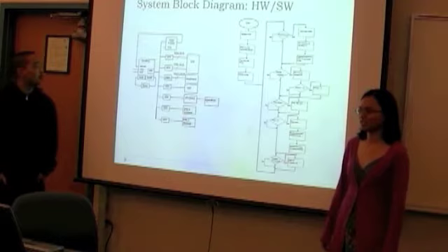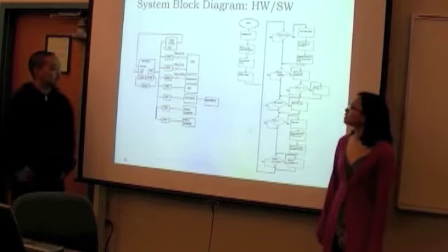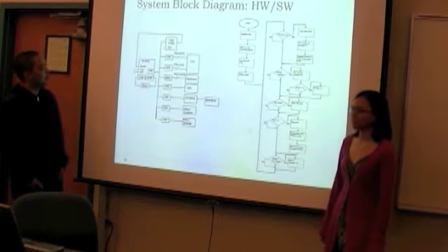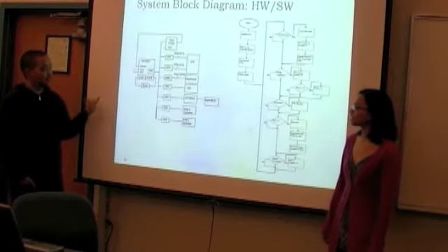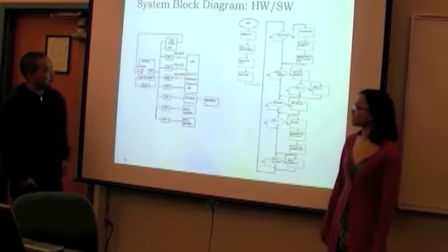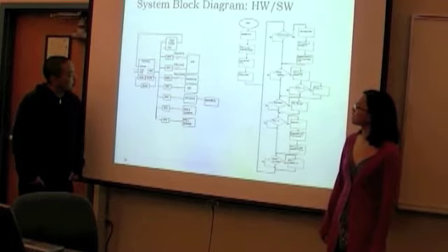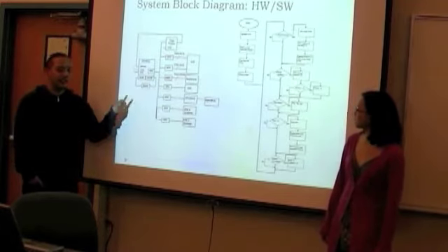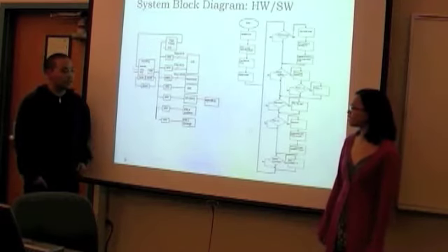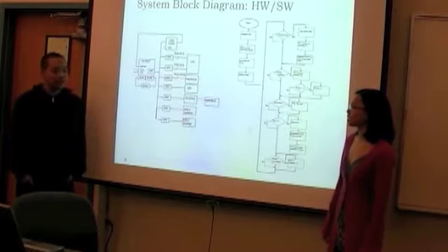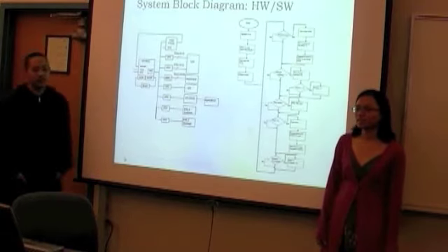Okay, first is our hardware block diagram. So we just use a timer counter to keep time for our whole system, and then we have the GPIOs, the data into control, which are for the LCD initialization and printing on it, and we have the UART Lite, which is connected to 24 keys on the keyboard, and we have the LEDs, but they were only used in our testing, and we have the SPI connected to a DAC, which is connected to our speaker. And we have button 0 to change octaves and button 2 to play our song.